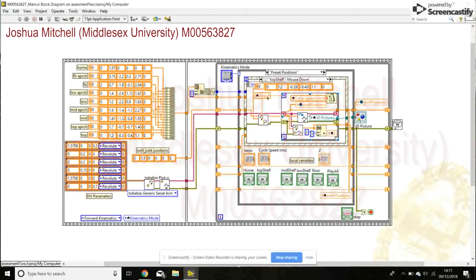So anyway, this then computes the amount of steps, which I showed you on the front panel, how that affects it, and will output here the interpolated trajectory positions. I could have used the Cartesian trajectory if I wasn't rotating, if I was to only use the X and Z coordinates, but because I had that rotate in there at the base, I had to use the normal trajectory.